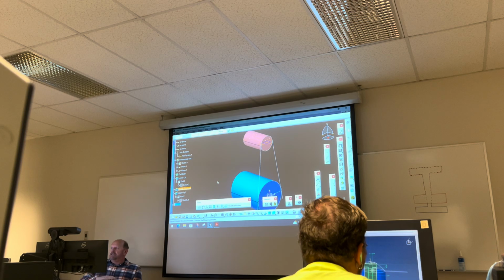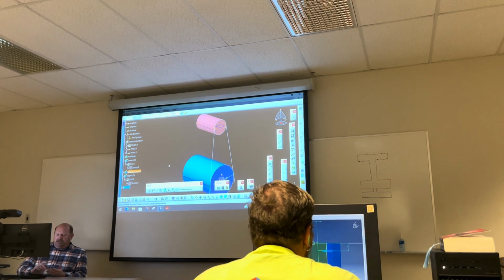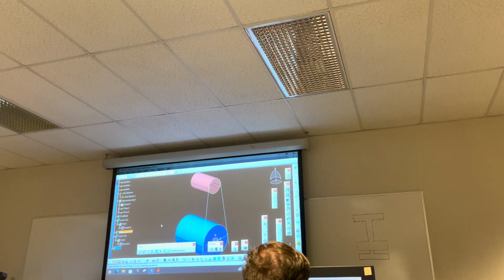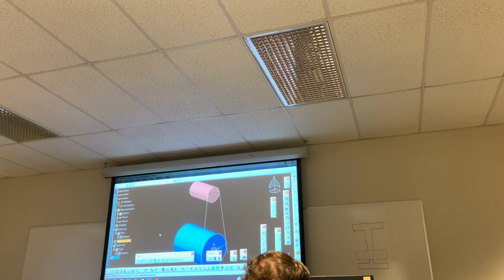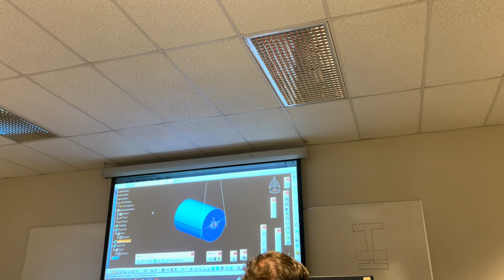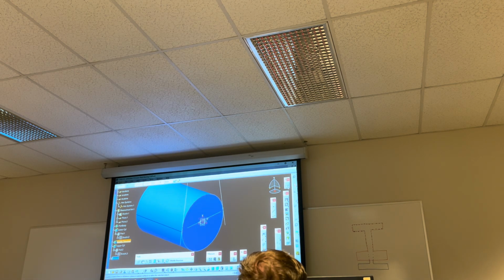So multi-section solids are probably one of the only ones where you can put multiple sketches in one body and it doesn't make any difference. Whereas when you're doing pads, pockets, other things, it's one sketch per feature, just so that it's what I would call a good modeling practice. So I'm still in that body, and I'm gonna go down here now and do the bottom sketch.